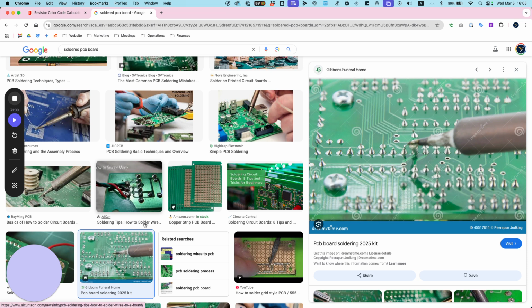Now let me show you, because you're going to have to bridge at some point. If it's a neighboring hole, you could just kind of pull it together, but if you're going to skip a hole, you should put another wire in there. So let's say, for example, we want to connect, I'm going to do row Q to S, because these ones are kind of screwed up. You see Q to S?